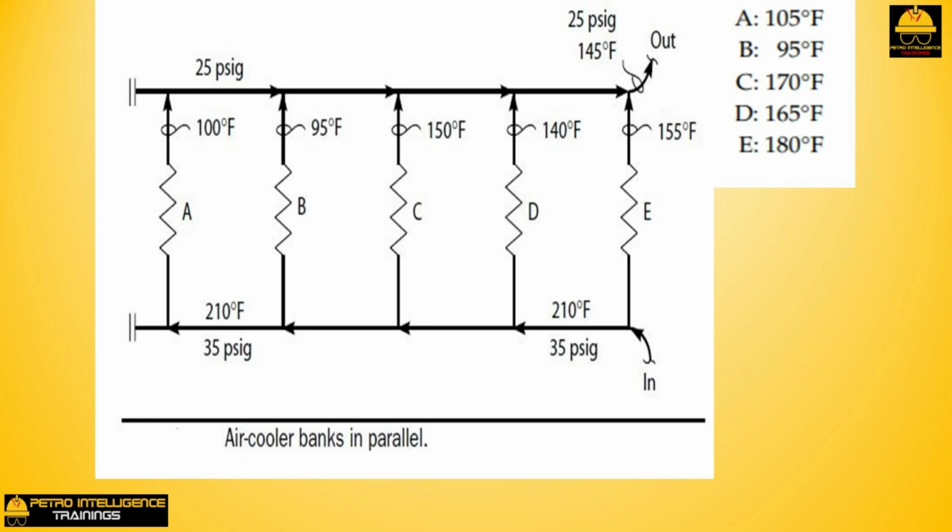These temperatures may be measured with a long stem, 24 inches, portable temperature probe. Do not touch the tip of the probe to the fins when making a reading. 4 readings per tube bundle section are adequate to obtain a good average. The ambient temperature was 85 degrees Fahrenheit.